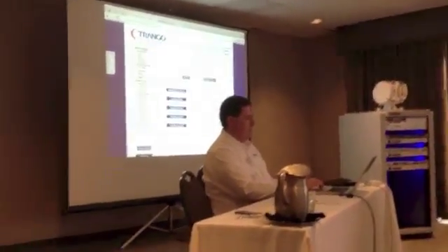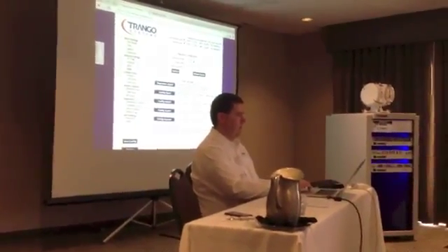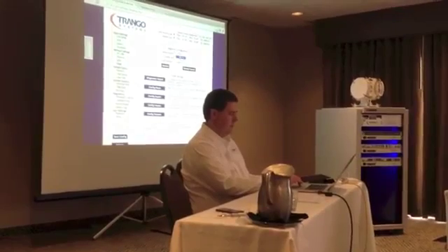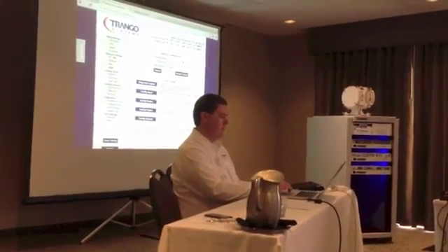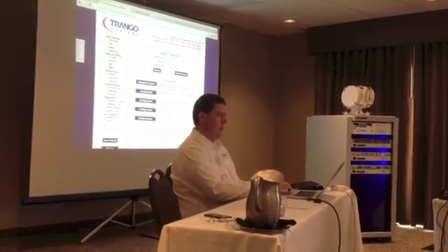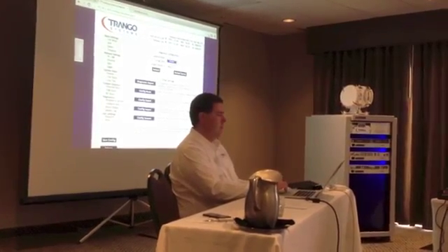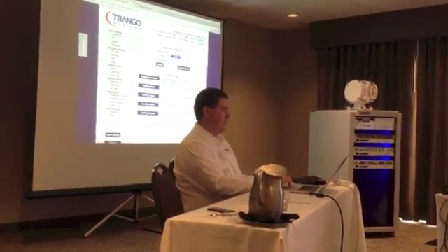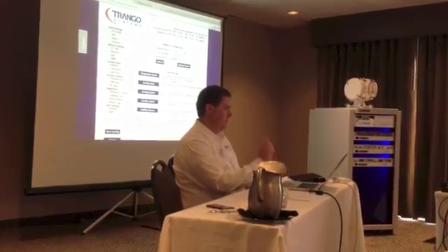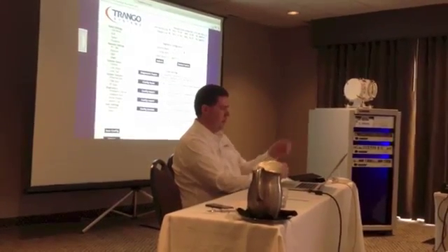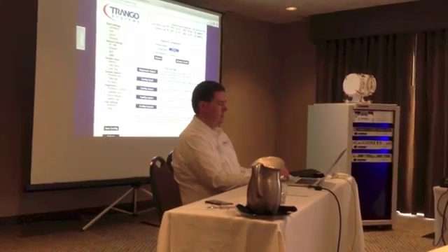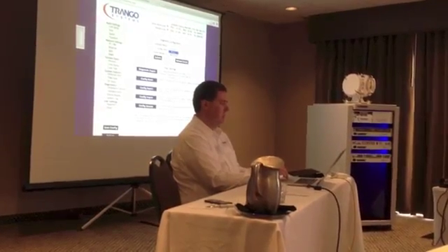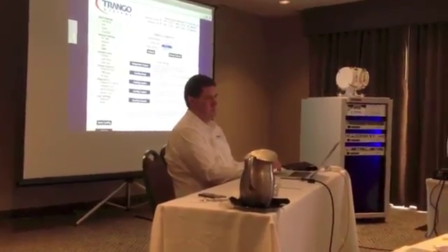Diagnostic options. If you've got one of these links back home and you want to have fun with somebody, go ahead and turn this loop back on to either one of these modes. They will love you for doing it. As we talked about before, for T1 termination, you could turn on one of these loopbacks and it will loop the signal back inside the IDU or the OMU, which is great for testing T1s. Not so fun for Ethernet.